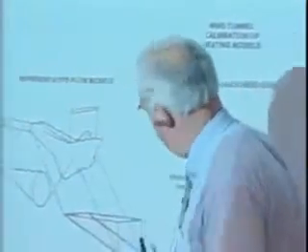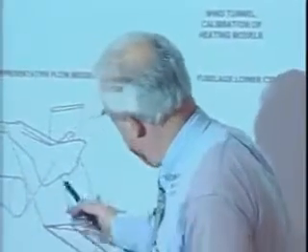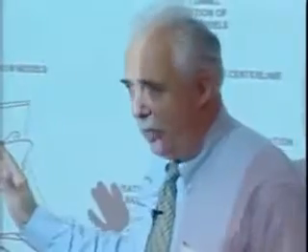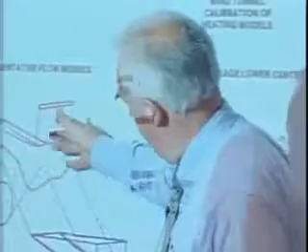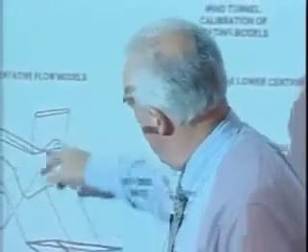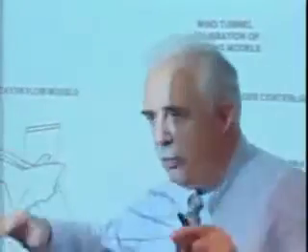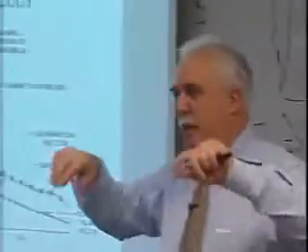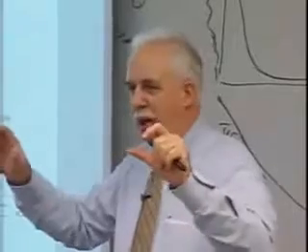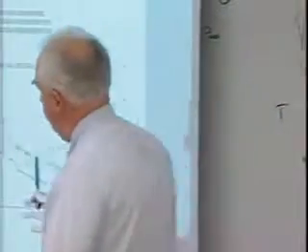I look at flow down the center line, and I'm sorry, this wedge, this is supposed to be a wedge or flat plate at angle of attack. This flat surface down here looks kind of like a wedge. Well, I can calculate a boundary layer on a wedge, given the pressure, which Newtonian would work fine, certainly in the blunt regions, and on a wedge I can do that flow. I can do a swept cylinder for the leading edge, and I can do a cone for where the boundary layer spreads. I take diagnostics in the wind tunnel, look at the boundary layer path, say, boy, this thing is spreading kind of like a cone, okay? This is the design methodology.